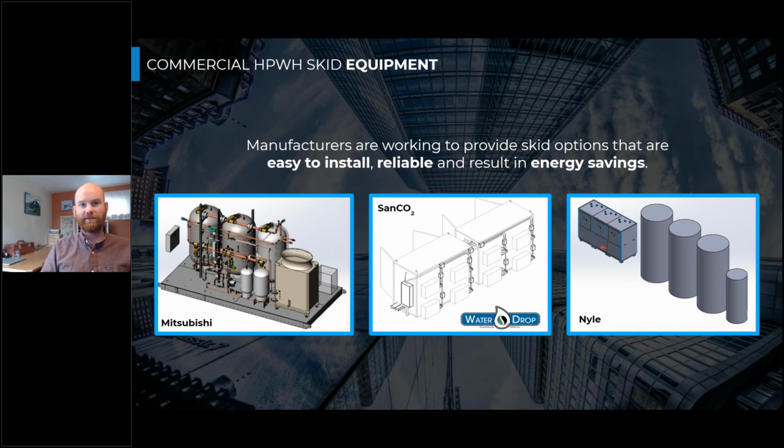And Nyle, also a manufacturer on the East Coast, they've been developing a skid system too that aligns with the Seattle Energy Code and utilizes a heat pump water heater in single pass to provide hot water to 3 storage tanks and a smaller swing tank shown there. So there's a handful of options that are coming out that are based on this plug and play application so that we can start seeing more of the market share with these heat pump water heating systems.